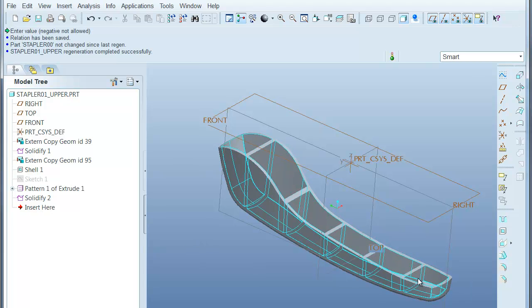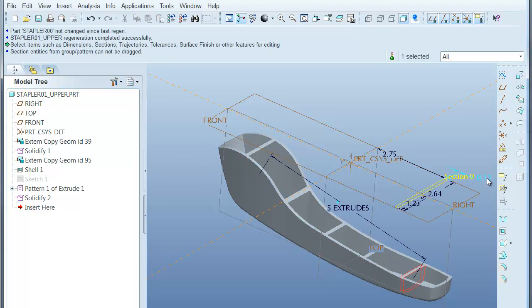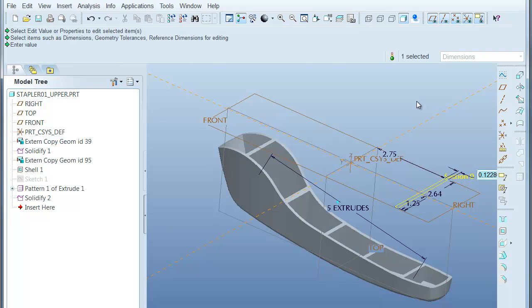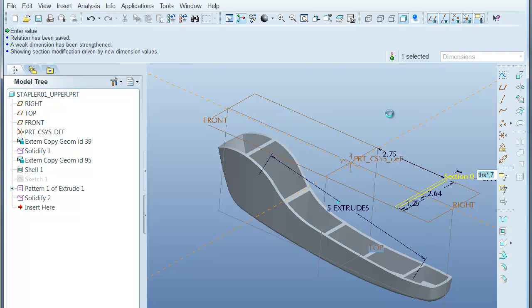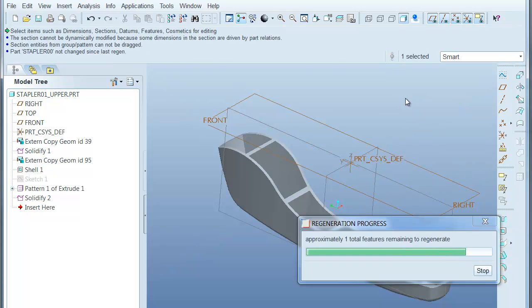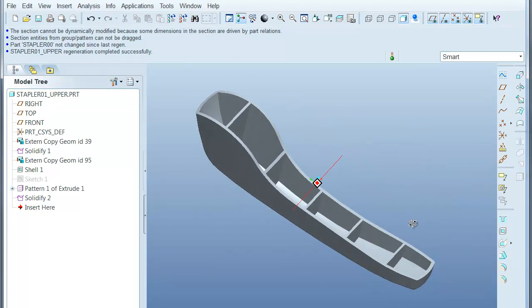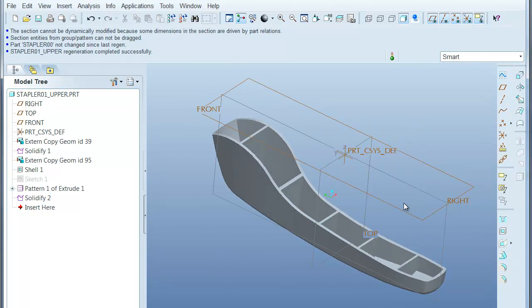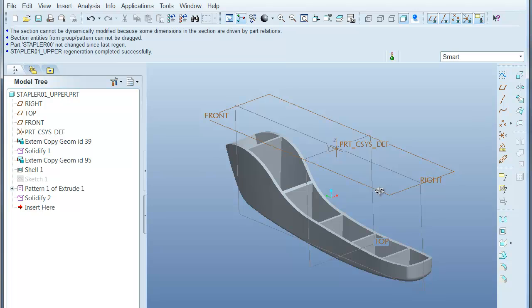And now I'm going to right click through here, and I'm going to set this geometry to THK times 0.7 to maintain the 70% rule. One of a couple hundred tricks for plastic part designers and die-cast people alike.